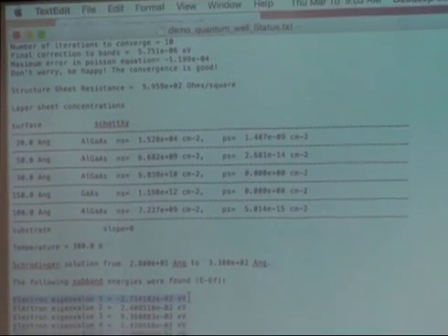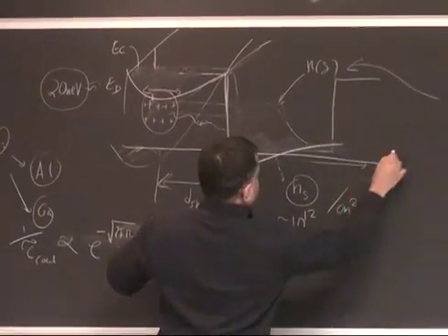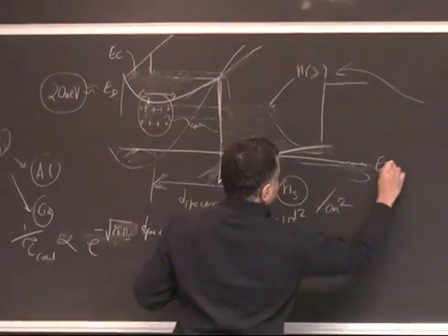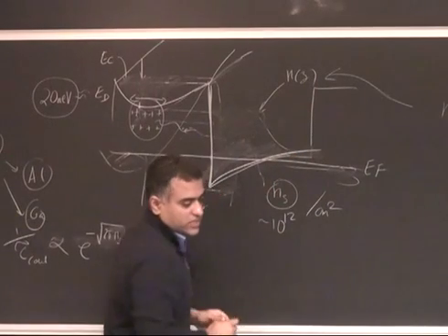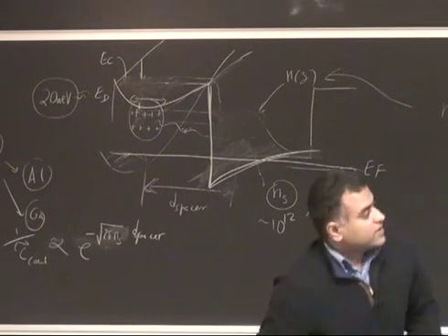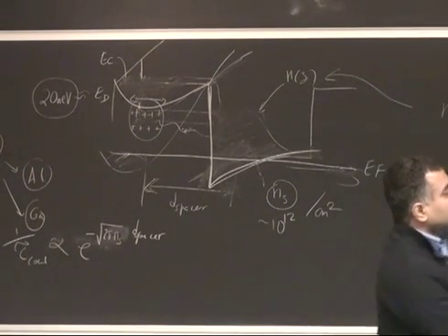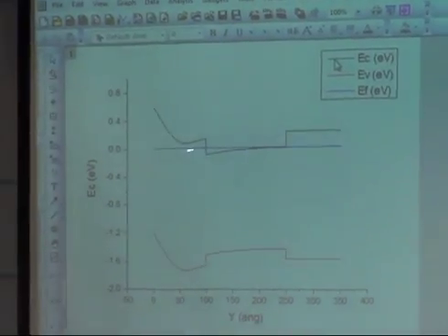let's zoom in into this region, all right? And the Fermi level is, let's say, here. This is the Fermi level. This is your conduction band profile, and it has gone below, and we just saw that here, right? So you see, this is the triangular well. Now the question is, how many bound states are there?